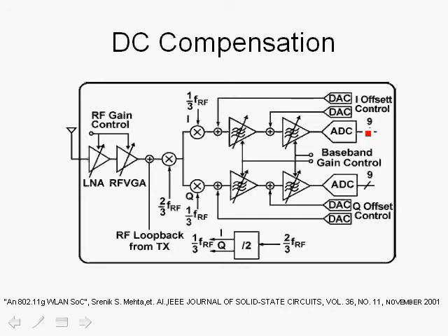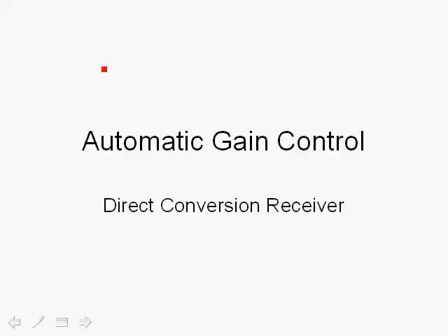The baseband digital signal processor also has to take into account that the amount of DC that has to be fed back and eliminated is also dependent on the gain. Therefore, there could be table lookups that associate different DC offset controls versus the actual gain. A similar mechanism will be used in a direct conversion situation, except that in the direct conversion, DC is more of a problem and added measures have to be taken.